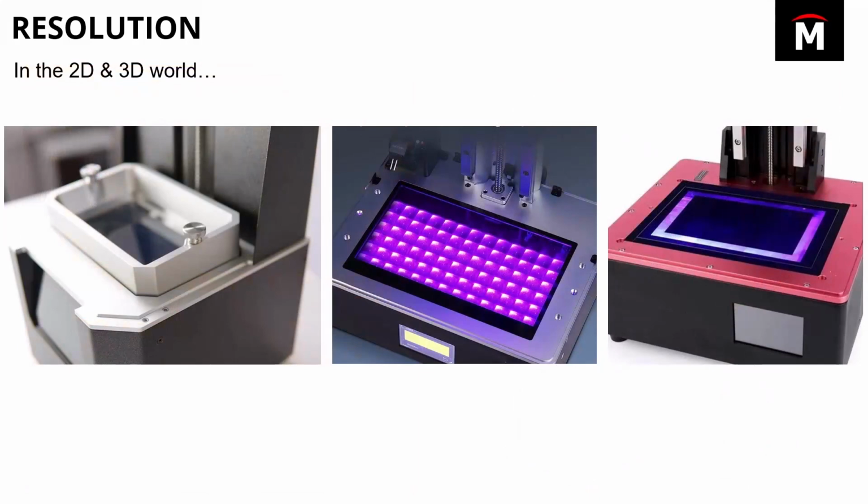Now, I'm going to throw a little bit of a curveball at you guys with a technology called MSLA, masked stereolithography. So you're taking the stereolithography technology where you're curing photopolymer resins, but now what you're doing is you're actually using a screen to mask with pixels areas off to let UV light in selective areas. Now what you'll find is you'll see advertisements for 4K MSLA printers, 8K MSLA printers, and what that terminology means is that's the resolution of that screen. So here you're combining kind of that screen resolution that we talked about at the beginning, with the 3-axis that's typical of 3D printers.